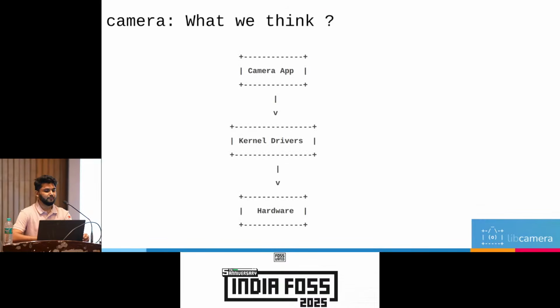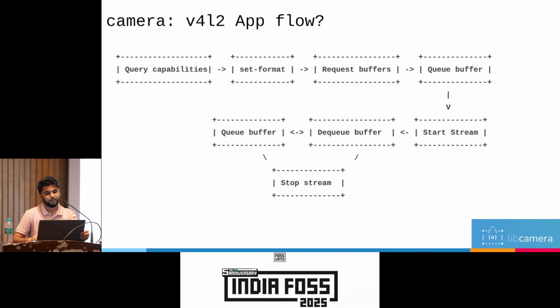When we think about the camera, what comes to mind? Many of you have developed a V4L2 camera app. A V4L2 camera app directly talks with the kernel drivers, leverages the hardware capabilities, and you get your images. This is a very simple and generic flow.